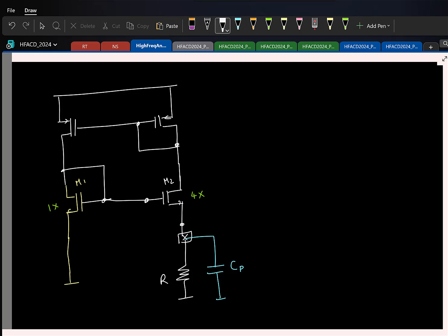And even if not, one typical thing that IC designers do is this. See, if you have some bias voltage generated on chip, it is a DC bias voltage. You don't want it to change, right? So to prevent any fluctuations in this voltage, what do you think we can put here? Yeah, a filter, basically. What's the simplest? It's a DC filter, a capacitor, right? There are multiple ways in which you can interpret it.